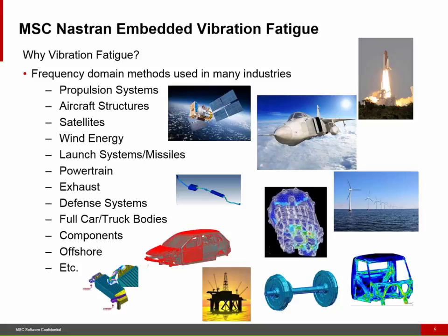So in the frequency domain, you often see benefits over time domain methods, and that's the intuitive way to find the dominating frequencies and study the eigenmodes that act at those frequencies in order to find the root cause of your structural dynamics problem. That is also valid when you go to the fatigue side. If you do fatigue in the frequency domain, you have a more intuitive way to find your root cause.